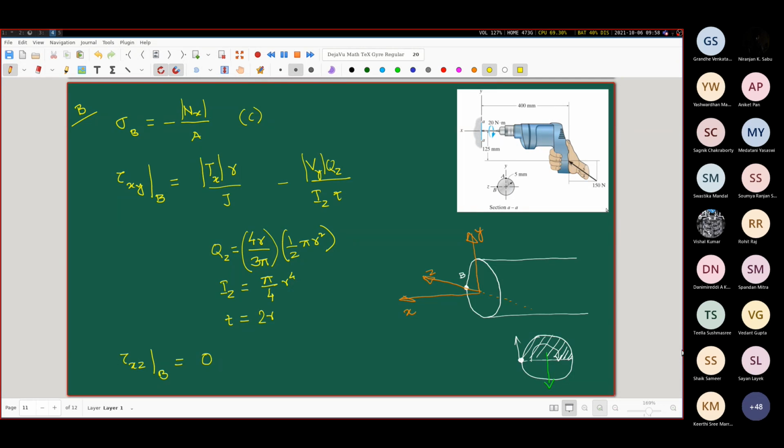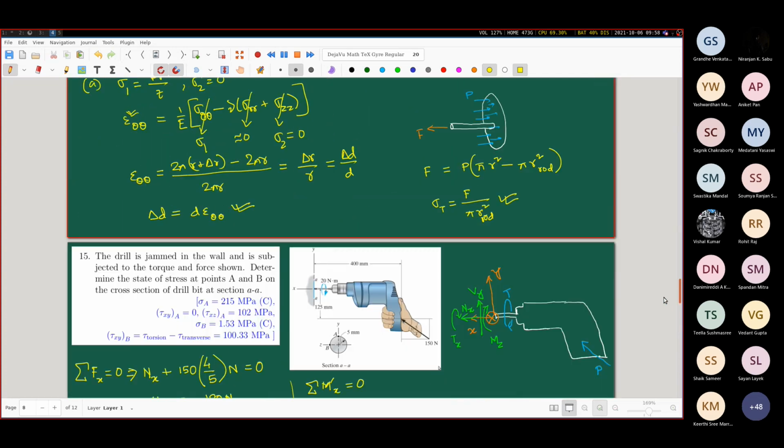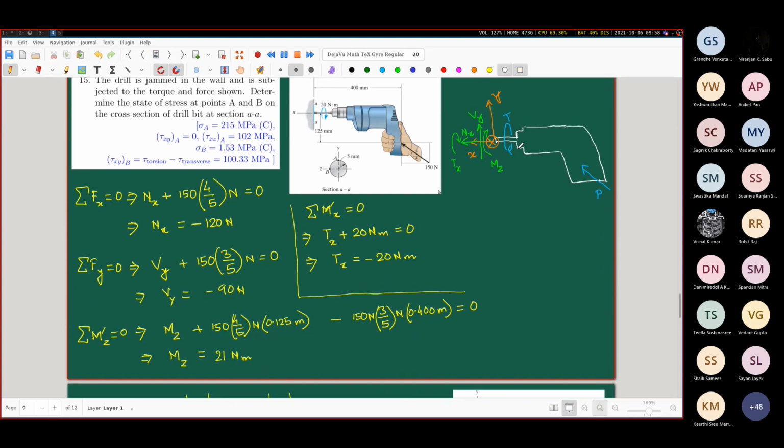Oh, I think I've understood what you are saying. Ideally, for your free body diagram, we should have taken only the drill bit. Yes, sir, that is it. Taken only the drill bit here. Then the torque due to the motor, which is somewhere present here, would have been like this, or maybe the opposite. Like this, and then this force would still be present, but in a transmitted sense here. The effect would have been the same, absolutely.